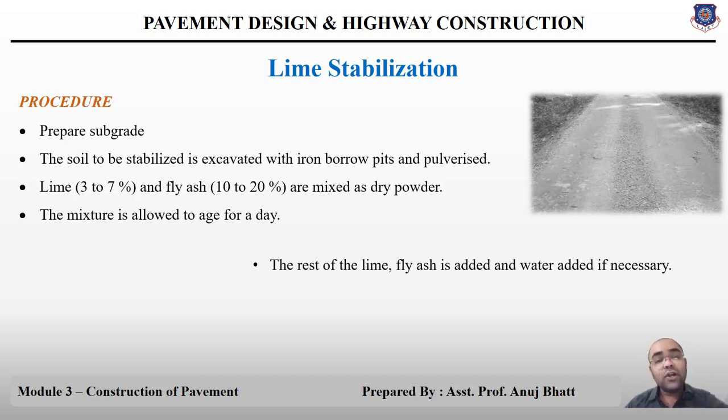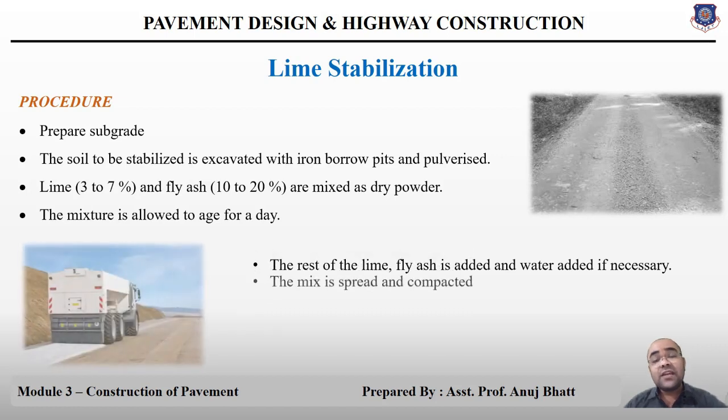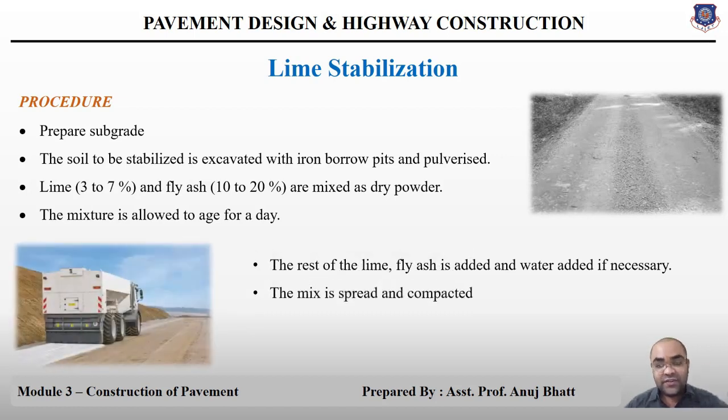Now your mix is completely ready to apply. The next step is that the mix should be spread on the surface, and after spreading the mix you have to compact it to the desired grade. After compacting the surface, the soil-lime-fly ash is cured by preventing it from drying. After keeping it for sufficient days, your surface is perfectly ready.